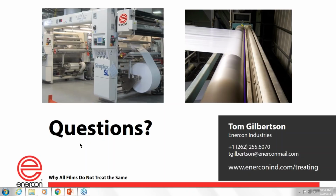And as you guys have heard me say a lot, and I'll repeat it again, corona always goes to the path of least electrical resistance. So if you get a carbon spot somewhere, that carbon spot looks like a better path to ground than the ground roll, and so it'll arc to that carbon spot until such time that the treater shuts off. So you really got to clean the electrode, make sure you don't have any burnt pieces of film, additives, dirt, debris. Clean that electrode and look at it regularly, monthly, sometimes even weekly, depending on your application.